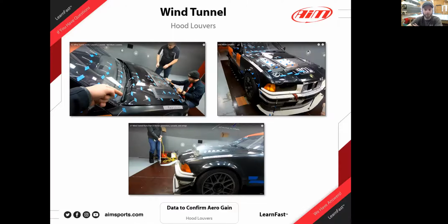Gotcha. Okay. Perfect. Do you vary the wind tunnel speeds or just keep it at a nominal number for all tests? Todd asks. I believe actual wind tunnel speed is 80 or 85 miles an hour, but they give you a whole bunch of data. And at that point, like that formula on the first slide, there's formulas for all sorts of stuff. In the data they give you, you can put in a different miles per hour, and it just extrapolates it up to whatever speed you want. In the real world, if you start going a little bit faster, you could maybe get separation off of something that you didn't at 85 miles an hour, but it's pretty close.